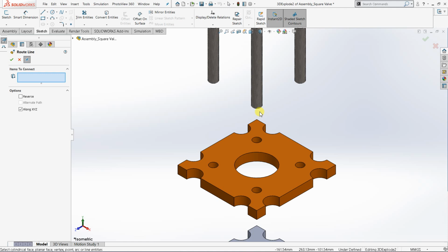and then of course definitely this bolt, you should reverse it, because the arrow is facing upward, it should be downwards. This bolt will go to here, then click OK. So you have to do it one by one. Same to this one. If the arrow is facing upwards, you need to click reverse, then click this one. So click OK, and then go to here.